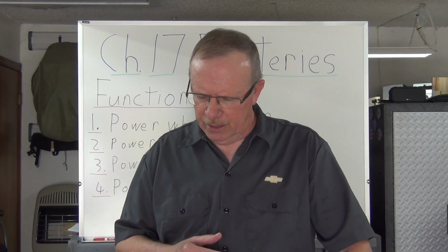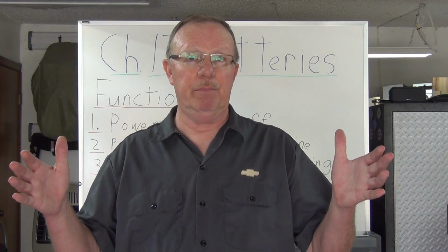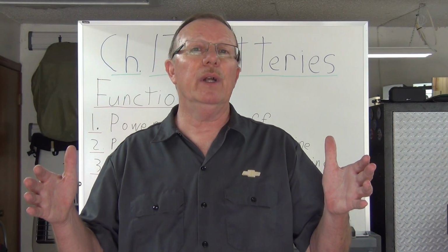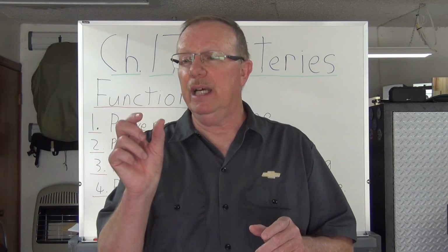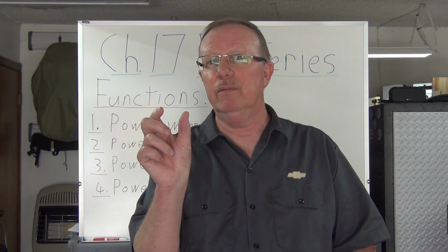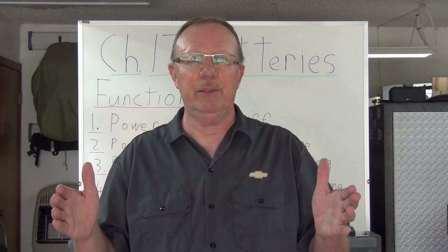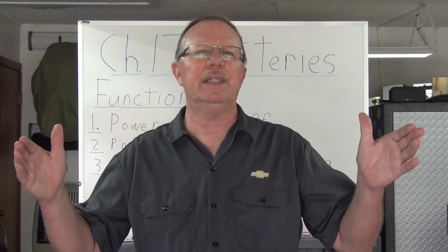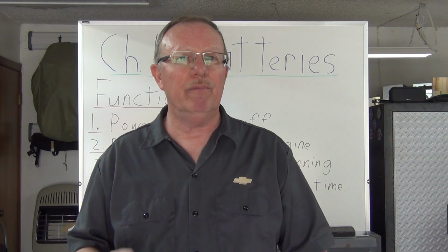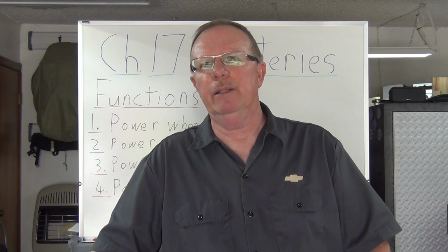Okay? So, the size of the battery is irrelevant here in a sense, as far as the 12.6 volts. Matter of fact, you can have a dry cell battery this big at 12 volts, but you can bet it won't start a car. Okay? But going back to lead acid batteries, if we have a lead acid battery that's this big, it may start the car, or we could have one that's this big. So the size of the battery doesn't determine the voltage. If it doesn't determine the voltage, then what does it determine?